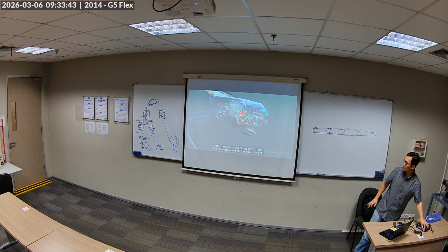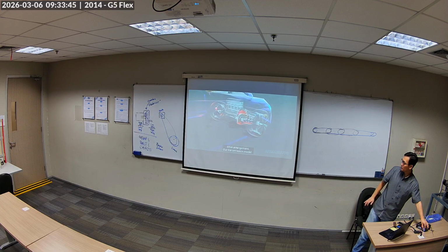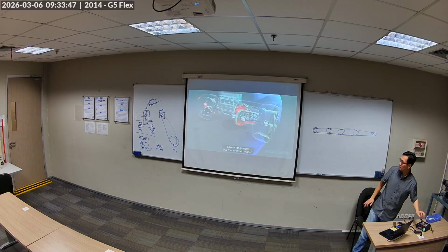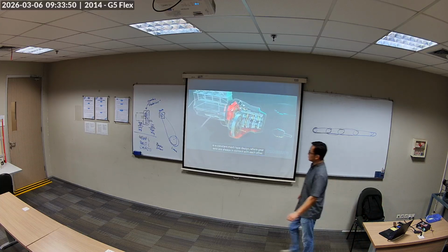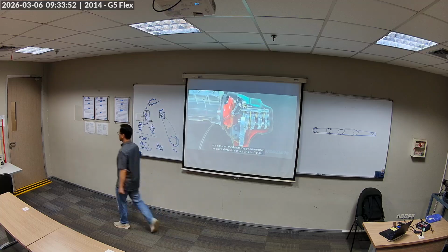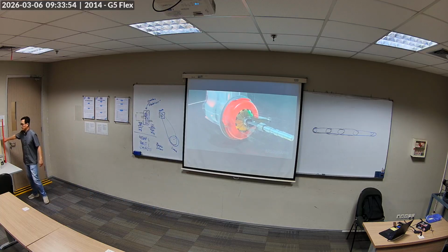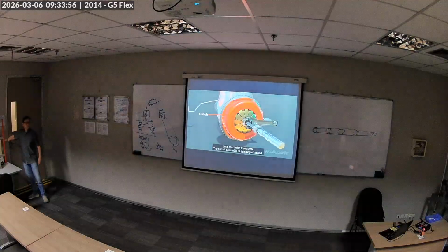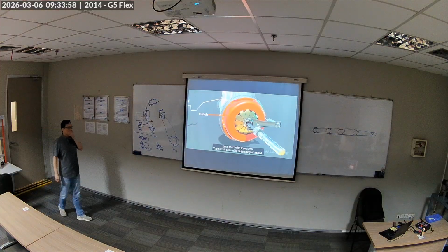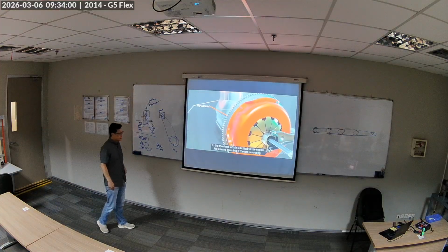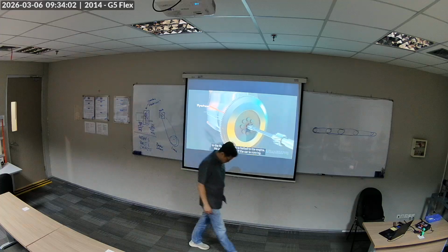For this video, we've chosen a front-wheel drive arrangement. Our transmission model is a constant mesh-type design where gear sets are always in contact with each other. Let's start with the clutch. The clutch assembly is securely attached to the flywheel, which is bolted to the engine.